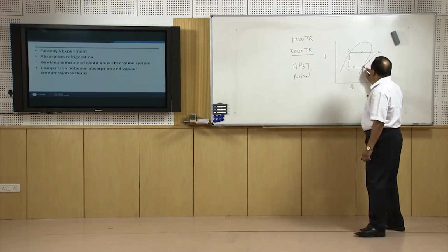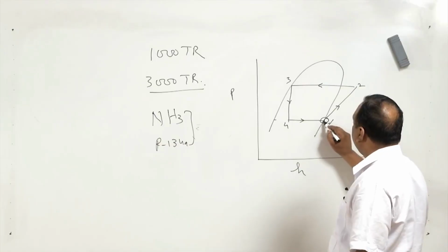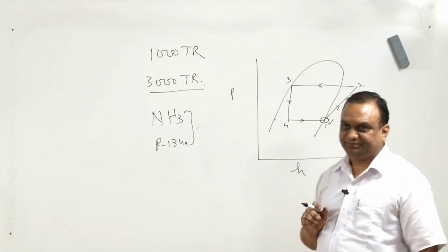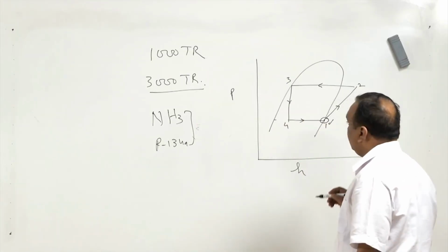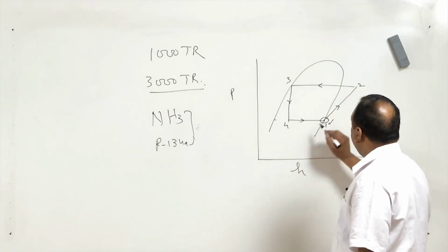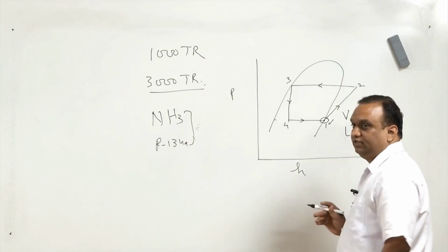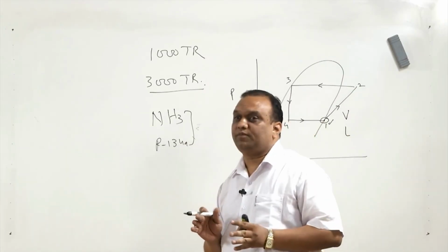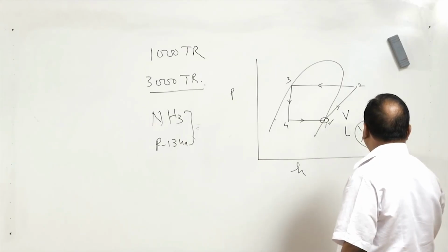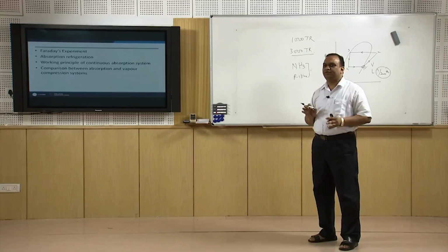Now, if we look at point 1, the vapor is saturated vapor or superheated vapor when coming out of the evaporator. The volume of the vapor is very large. For example, if we convert this large volume of the vapor into the liquid, the volume of the fluid can be reduced by 1/200 parts, or it ranges between 150 to 200.